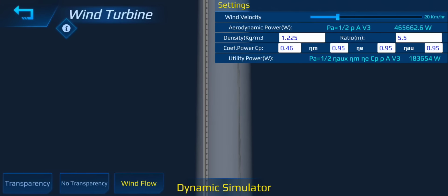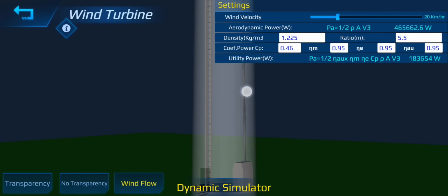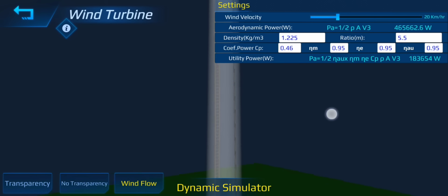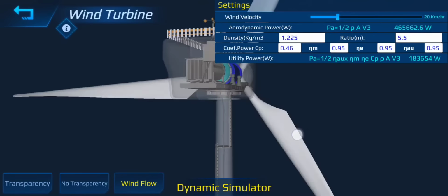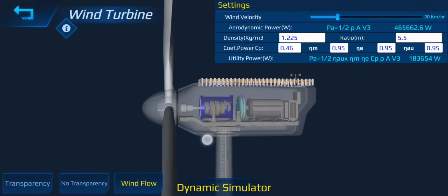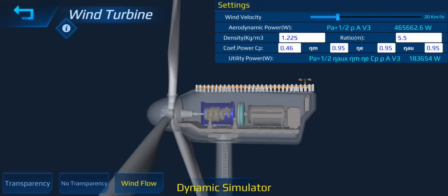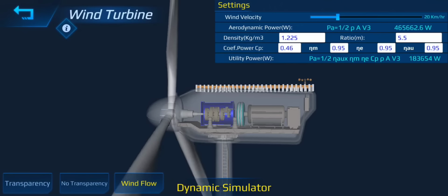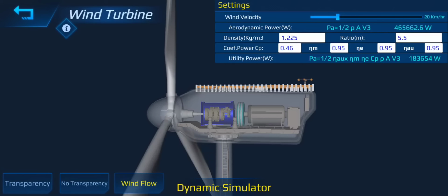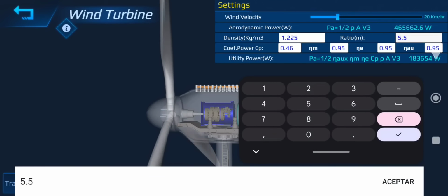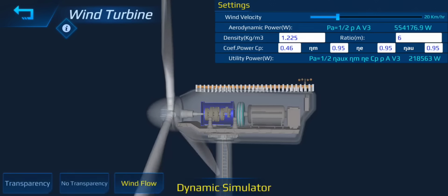We have in our equation an uncomfortable factor, which is the time t. The energy obtained, obviously, depends on the time that we remain measuring. For this reason, power is a much more suitable magnitude, since it does not depend on time. Power is equal to energy divided by time. Taking into account the results obtained, P equals eta 0.5 pi rho r squared v cubed t over t equals eta 0.5 pi rho r squared v cubed.